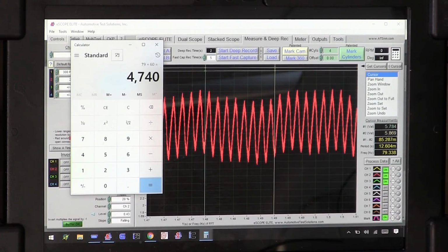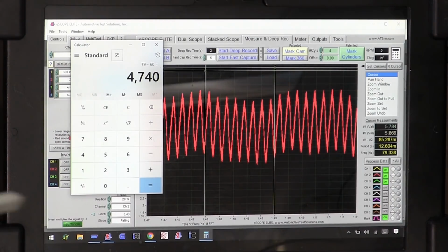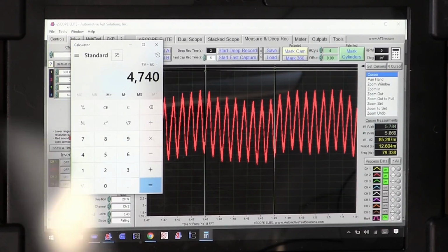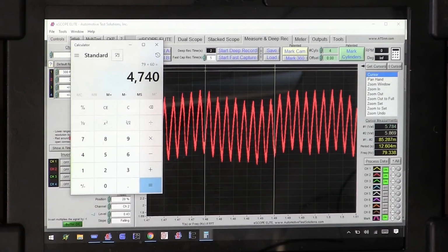So we now know that the line is restricted. That's a huge gain, because if this was cavitating, this pump would be all over the place. When it gets air and it's cavitating, it'll go up to 7,000, 8,000 RPM, and then it will load again down to 4,000 or 5,000. But the pump moves up and down, and that isn't what we see.